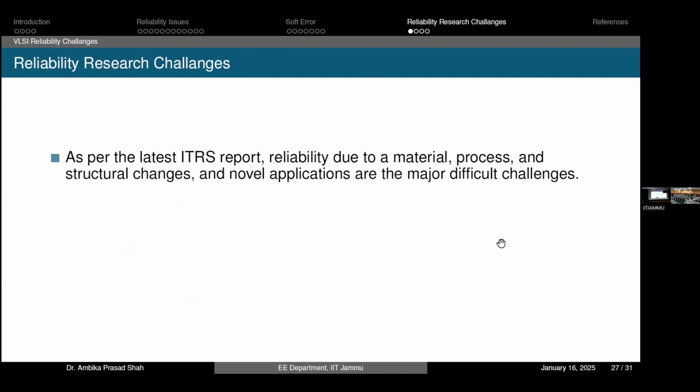Single event transient. That is, yeah. So it depends. Very good question. Let us assume I have some memory having more than 2 storage nodes, because if you see the recent radiation hardened memories, there are too many storage nodes, but other than this, there are other secondary nodes which can decide the logic. So if a high energy particle is striking at more than 2, that can be a dual upset or multiple upset. That is also possible.